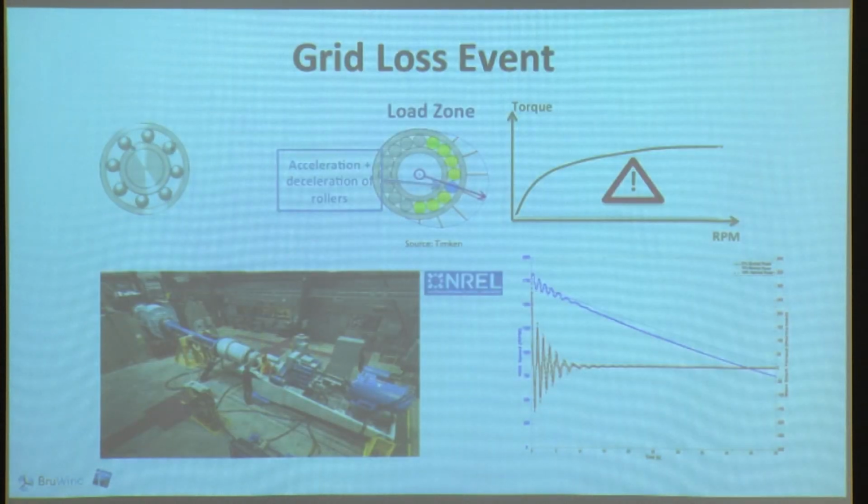So it made us think, okay, can we do something with this? So we did a test on the dyno. What you see here is a complete nacelle inside the lab. We can apply 6 degrees of freedom loading at the front, so basically all the rotor loads can be introduced. And we have a microgrid, so we can simulate the electricity grid as well and do dynamic events. The component we are looking at is the high-speed bearing, the one that is very susceptible to failure.